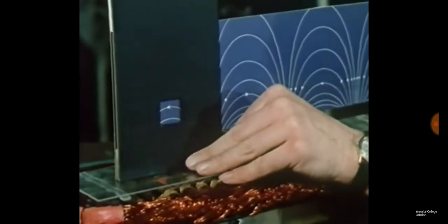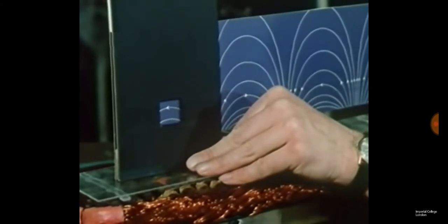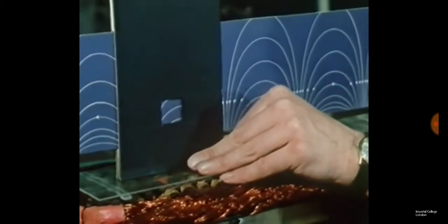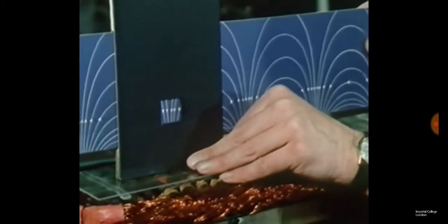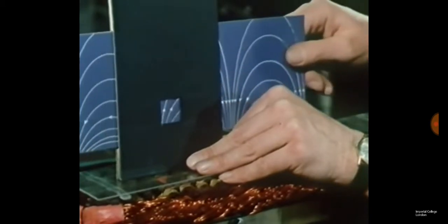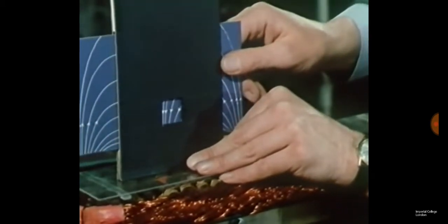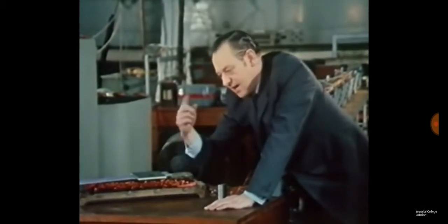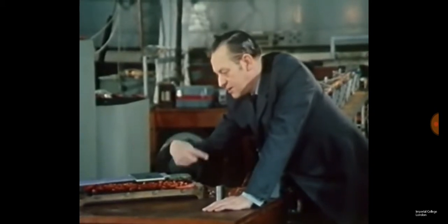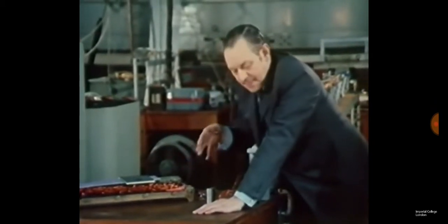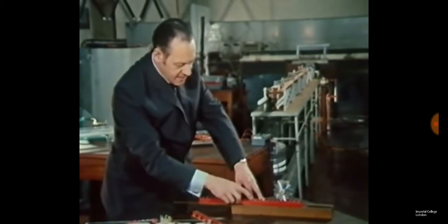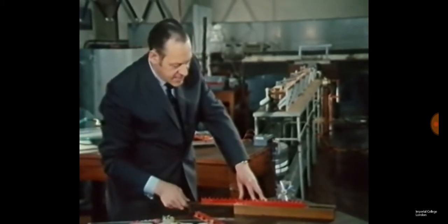Notice the direction of the arrows. At the moment, the field is to the left. Now it's upwards, to the right, downwards. Left, up, right, down. And the rotation, you see, is clockwise, which is to say, rolling backwards. So the whole machine behaves like a mechanical rack and pinion, in which this is the field and this is the rotor. And here is the action.